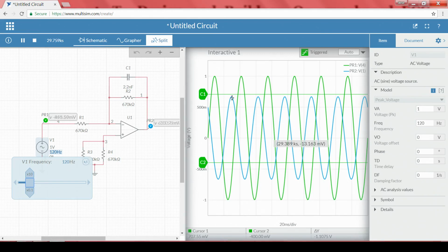In order to visualize using a time domain signal by looking into a CRO, one way is to slowly increase your input frequency until it reaches the 3 dB line, which is 0.707, that is 70% of your maximum voltage, that is nothing but 707 millivolts. Whenever the output voltage is lower than 707 or just at that point, that frequency is our cutoff frequency. So, we have seen that it is somewhere around 108 hertz, right.